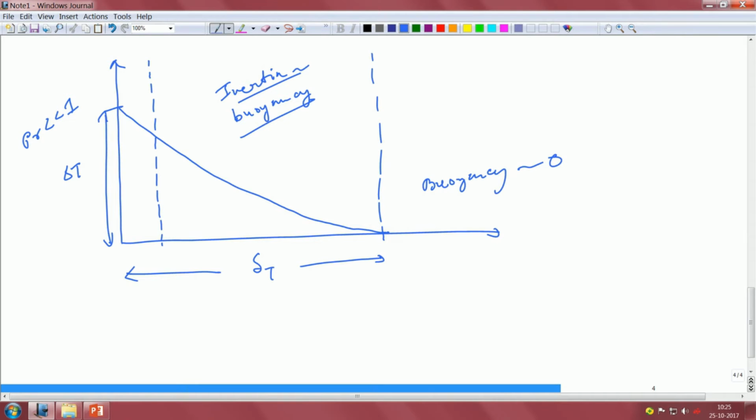So, naturally there is no velocity scale that is possible. So, the velocity profile must be as wide as the temperature profile, that is about it. So, that means whatever velocity profile we are going to draw, it should have a maxima somewhere, and it will be 0 on this side and 0 on the wall side. Wall side it has to be 0 regardless.